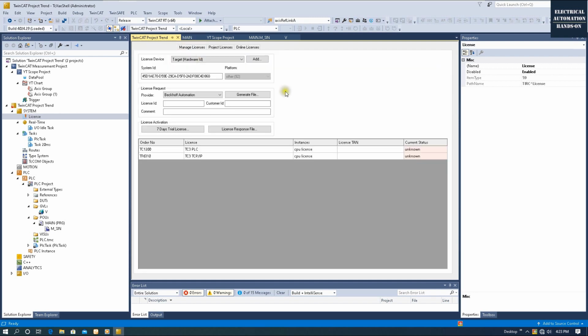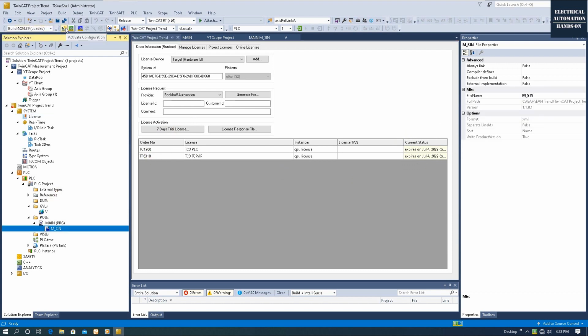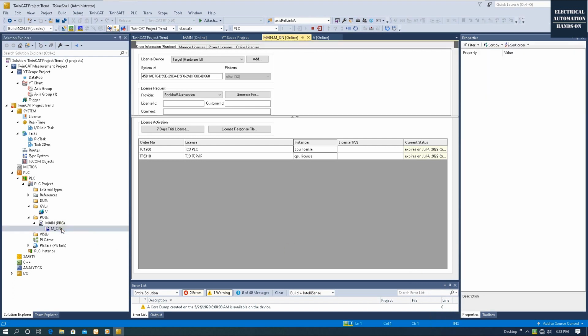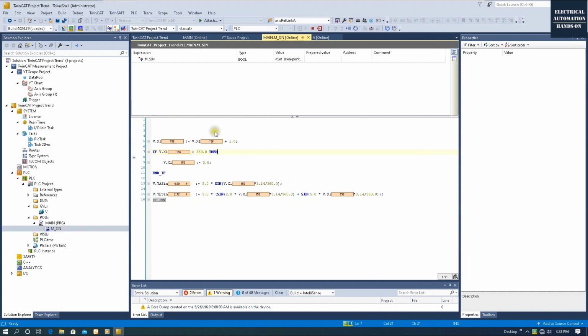If I shift over, so we'll see, here got refreshed. Okay, this is the PLC license. Now we download this hardware configuration and then let's click this login. So we will download the PLC program. Okay, once we see the icon shows like this, green, and here it shows the green has a yellow gearbox running inside, so it means the program we downloaded and we are online.